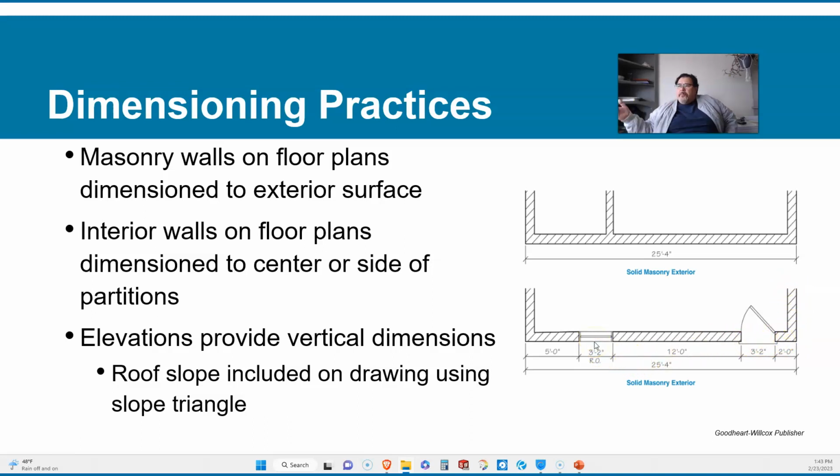And then a plan view represents a section. So I'm cutting through the wall at 42 inches in height. So I'm going to be cutting through a window or a door. So at those particular heights in the plan, that's what I would see, is the framing of the window or the framing of the door. All this is showing me some of it, like slice half of the door and slice half of the window. A detail would give me a better accurate view, closer up view.